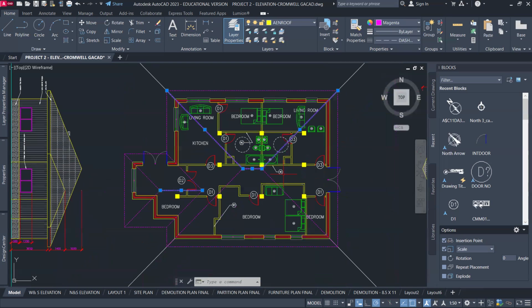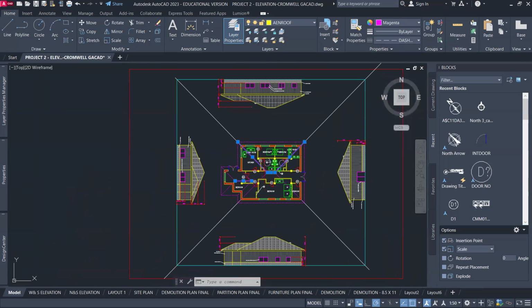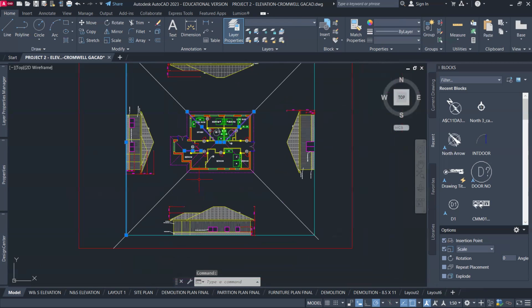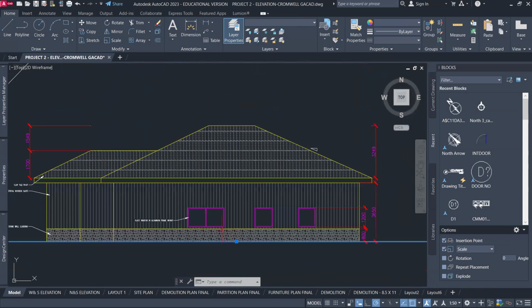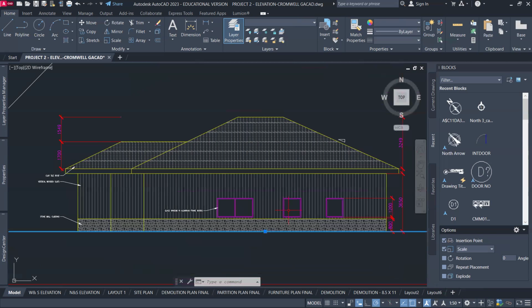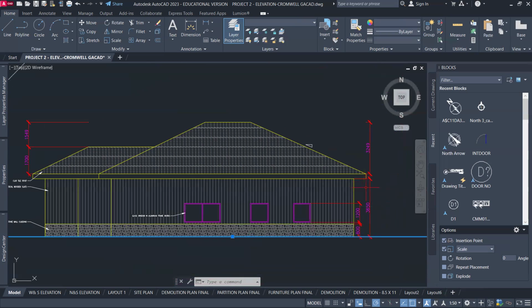Once you have done your 45-degree angle, you can stretch that 45-degree line up to where you can draw your first ground line. The ground line is a lot farther away from the building, so that the heights of the elevation will be beyond the building.